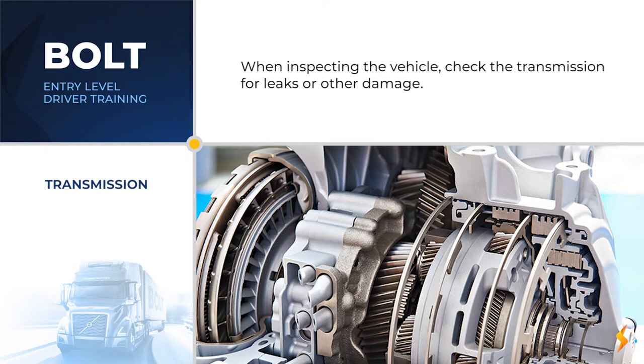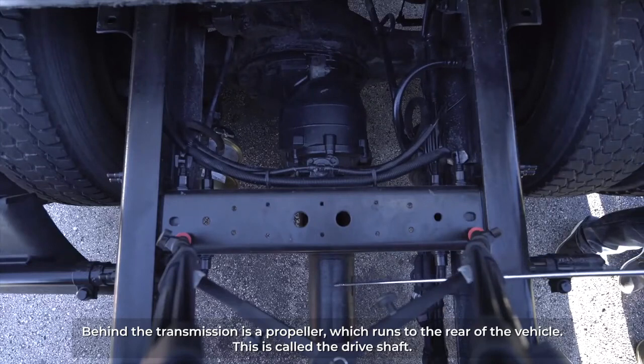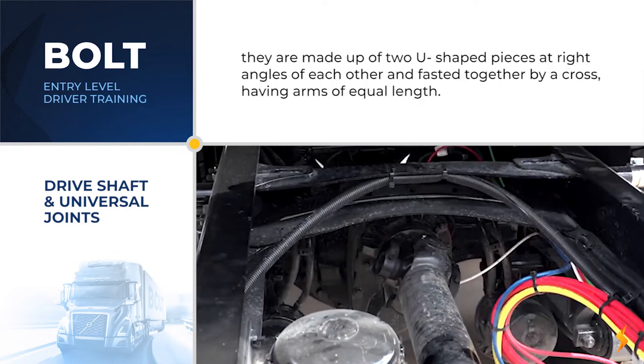When inspecting the vehicle, check the transmission for leaks or other damage. Behind the transmission is a propeller which runs to the rear of the vehicle. This is called the drive shaft. The drive shaft is a hollow shaft that connects the transmission to the rear of the vehicle. At the front and rear of the shaft are universal joints. They are, in most cases, made up of two U-shaped pieces at right angles to each other and fastened together by a cross having arms of equal length.